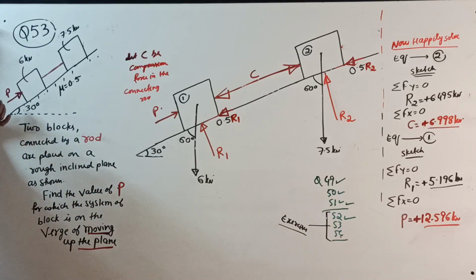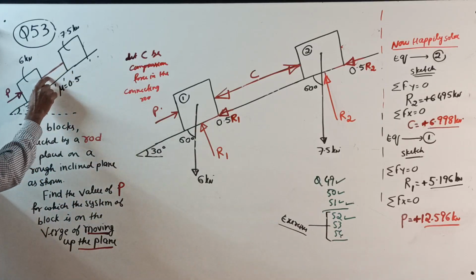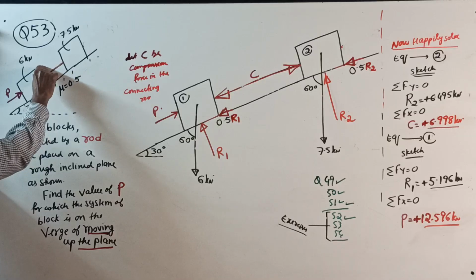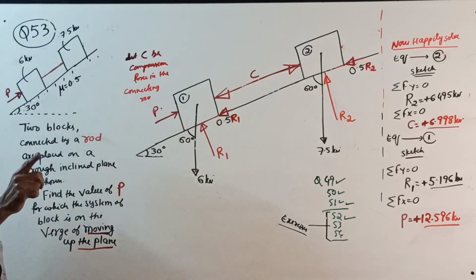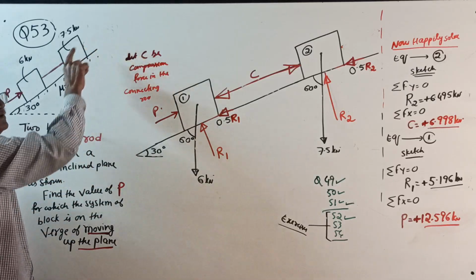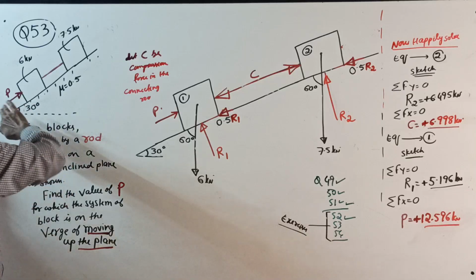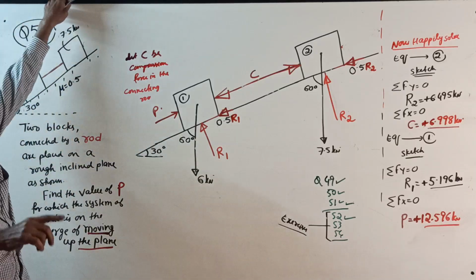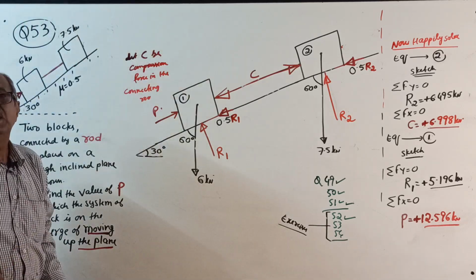See, when you apply a P here, if you put a cable here, what will happen? When you apply the force, as it moves, the cable will fold. Now you should have a solid member. Cable will work if you apply force here, that is a pulling force. It's a pushing force. Pushing force means this member is in compression. Now cable they cannot give. If they give cable, they do not know the subject.